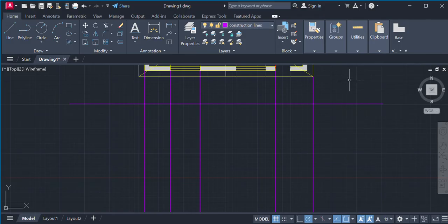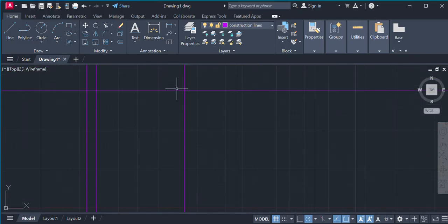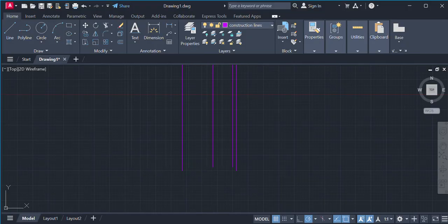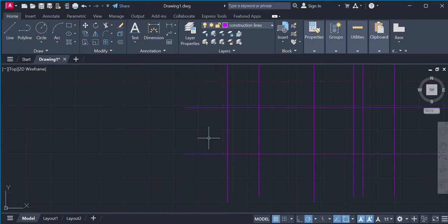Okay, so normally our roof height will have a specific angle. But let's start from the bottom. So here I'm just specifying that nothing goes above here, and if we ever need more space, we can always move everything, right? So let's just be safe. Let's start down here, and we said we have a floor height of 2,400, 2.4 meters. So we can offset that. We're still gonna create the foundation and stuff, so don't worry much about it. So here, this is just the floor to the roof. Okay, are we together? Are we clear?